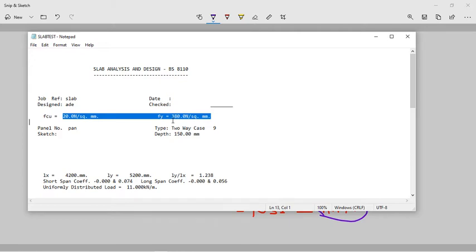So after, I think they were at finishing stages when the result came, and the design for the structure was based on 410 Newton per mm square. But when the result came, they found out that it was around 200 and something that the result brought back for the tensile strength. In fact, he was shocked.